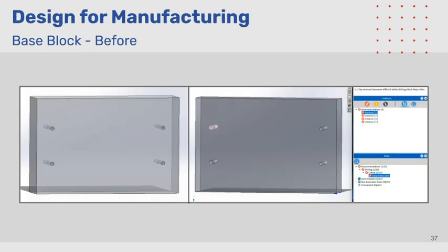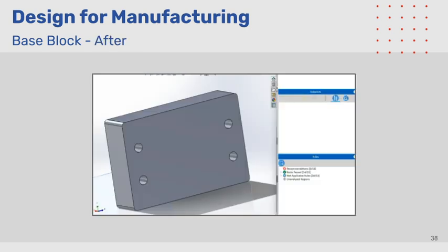The second part redesigned was the heavy base plate, which allows the pasta maker to sit on the countertop rather than being attached by a vice grip. This part must be machined as it is made out of a steel block. As per DfM rules, there was an issue regarding the small deep holes while machining. The deep holes would pose an issue for chip removal while drilling. Additionally, the team decided the sharp corners could pose a safety risk and as a result would need to be filleted. In order to fix these issues, 5mm radius fillets were added to the four corners of the design and the holes were made larger. The material cost for this design is $10.68 and the machining cost is $2.86. The price is the same as that of the pre-DfM design, as both parts have the same dimensions and require the same steps for milling.